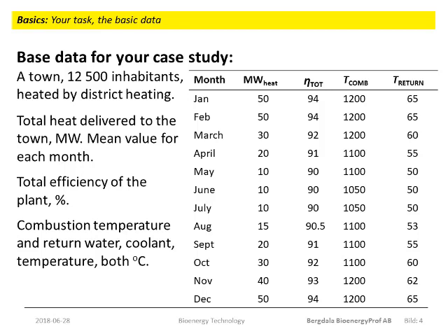Through different handling the energy company adjusts the fuel quality a little bit, and during winter, November, December, January, February and March they use the best fuel, and then they have a combustion temperature at 1200 degrees. In June and July they use the very worst fuel, and then they only have a combustion temperature at 1050 degrees. The other months the combustion temperature is 1100 degrees C.